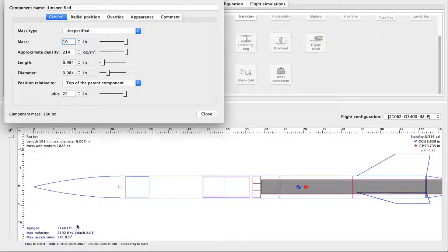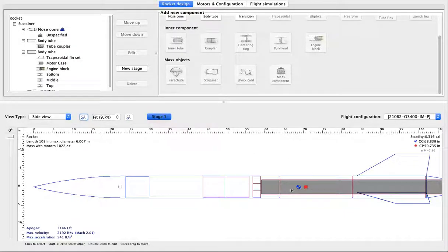In fact, our apogee just shot up. If you wanted to run the percentages, it's probably something unfathomable. 30, I don't know. I'm not going to try. 3,000%. So we have our mass up here, and if we want to really increase the stability, this is where the fun kind of begins, because you want these guys apart from each other so that your stability is between 1 and 2 the entire flight. It's great to start out with a great stability, but the big thing that people forget, when we take out this motor, which means after it's all burnt up, this is how stable we're going to be.